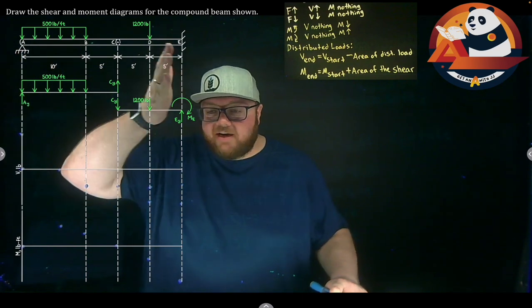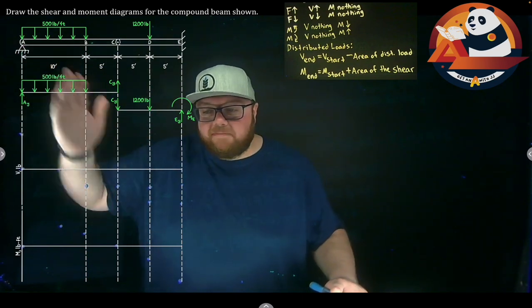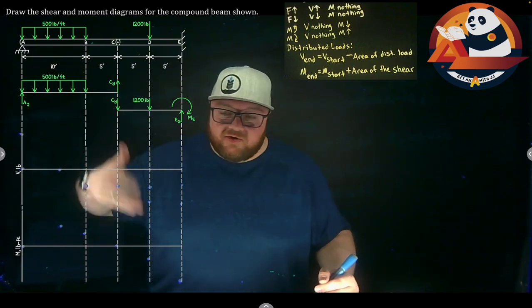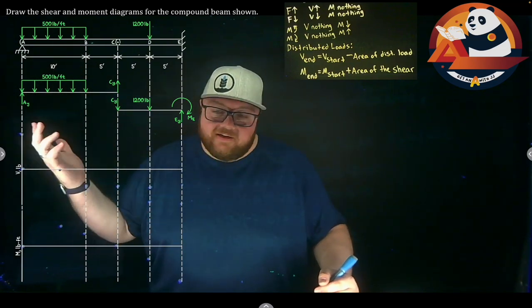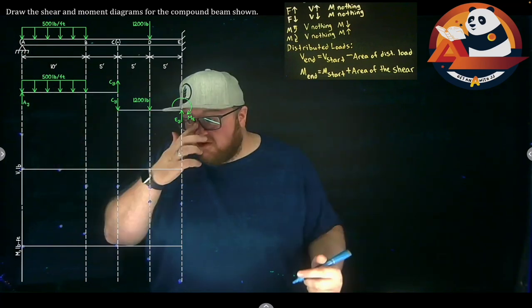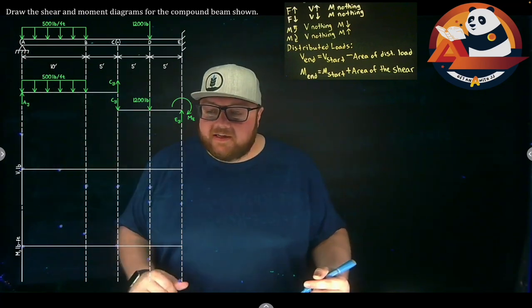Technically, we don't have enough equilibrium equations to also get the X components in here. That doesn't matter for us, though, because we're looking at shear moment, so it's only straight up and down, and moments from that. We'd be able to say that AX equals EX, and that's all the farther we really need to go. We'll ignore those pieces.